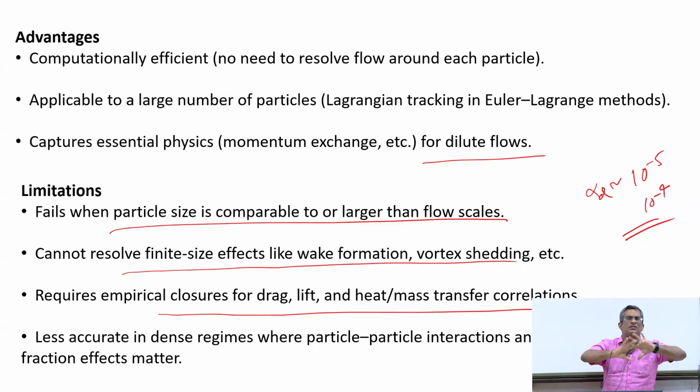If you fully resolve a flow, you do not have to model, for example, drag. You do not need any drag model, for example, the Stokes drag model, because you are resolving the boundary layer around individual particles. So, you calculate the force directly. You do not have to use any model, but in this case, you will have to use the models, and you are restricted by the assumptions in the model. For example, Stokes drag is valid only for a certain range of Reynolds number.